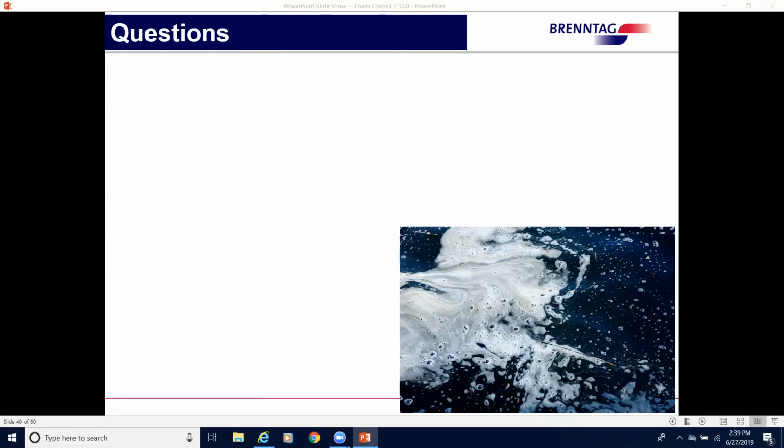It really boils down to, no pun intended here, how big the lagoon is, the feed location, and how effective the product is. I've seen it be effective. I've also seen it be somewhat of a miserable failure. So anytime you can cast the defoamer out more into the basin over a wider area, it can always help you quite a bit. So hope that answers the question, but that's at least one of the experiences I had with some of the steel industry applications in the Pittsburgh area.